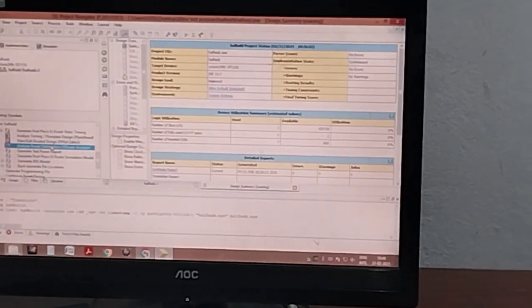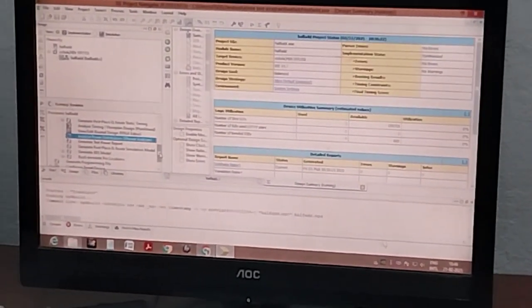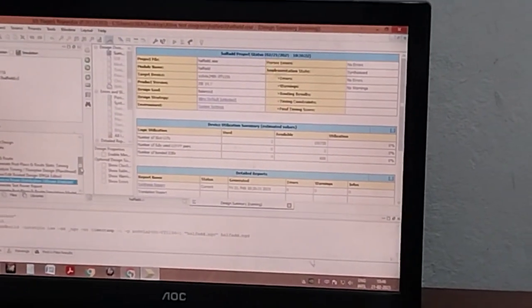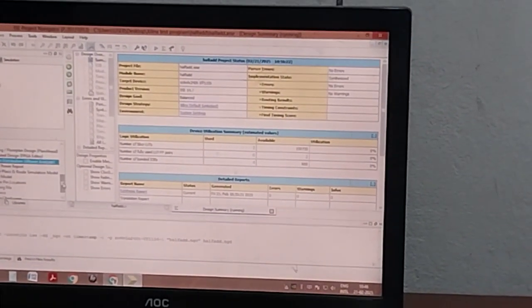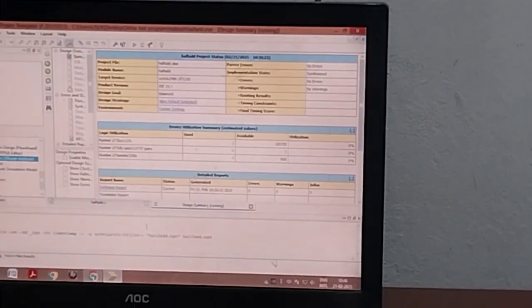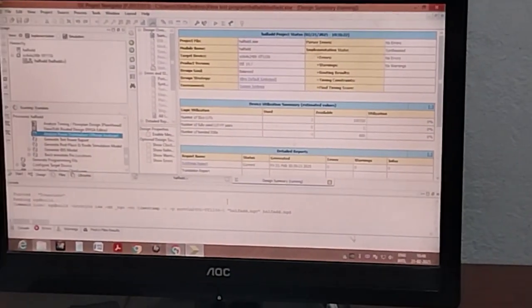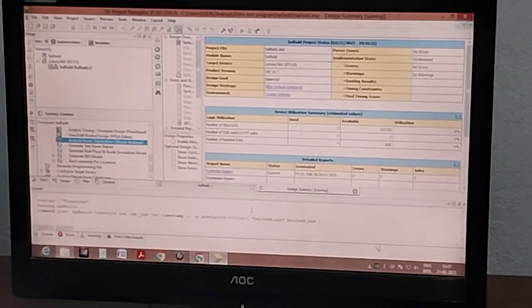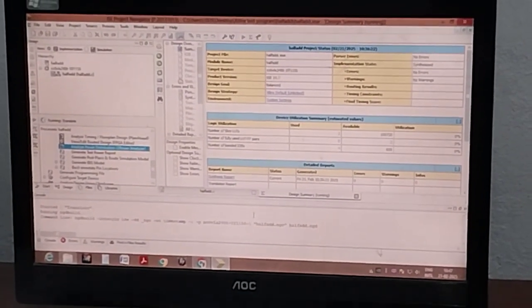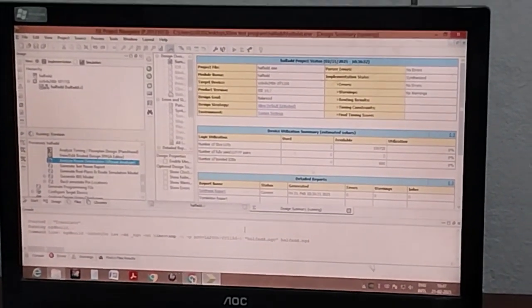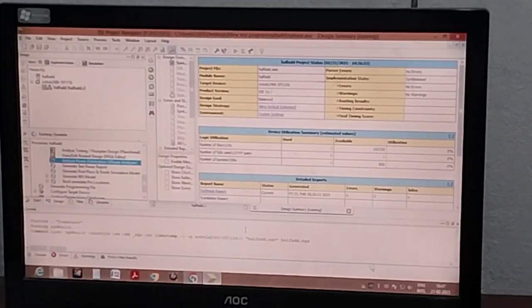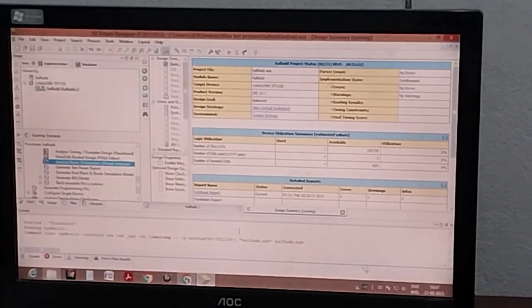You can see that it is taking some time. Whatever is now translating, then mapping, place and route, will take at least 2 to 3 minutes. If you see your design in the Virtex 6 hardware kit, that code will be downloaded in that particular Virtex, but here basically you are not downloading any code. For that you have to connect with the proper JTAG.